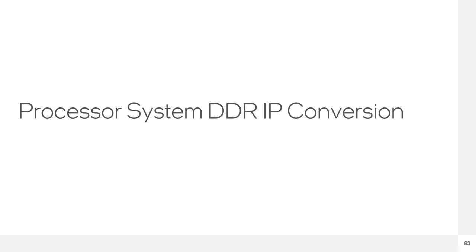In this section, we will provide an overview on how to convert the processor system DDR IP on UltraScale Plus MPSoC to the Agilex 5 FPGA HPS EMIF. We will look at the IP used and how to map the Zynq IP settings to the Agilex 5 HPS EMIF IP.